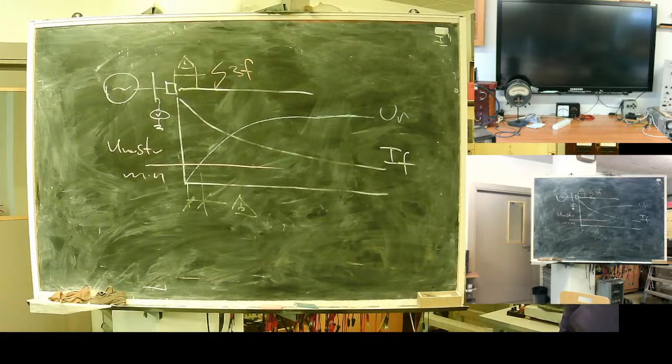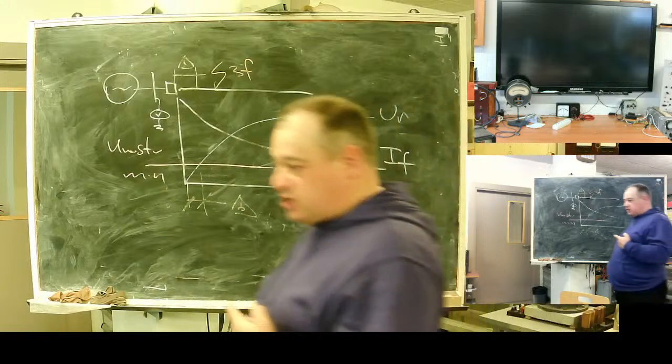What to do? At first, modern directed relays have a memory. In case of three-phase fault, they can take from memory direction of voltage before fault. But it will not help here, because before we had 0. We have a switch on fault condition.